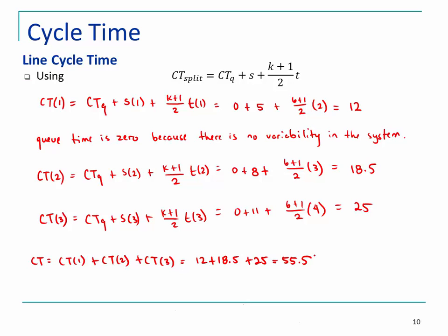But what happens here is that you're not considering any of the overlapping components of the cycle time. For example, you're not performing that setup for each part. When you're performing that setup, you can have other parts running on the other machine. So what I mean is, this computation right here is not correct because it is ignoring the overlapping.